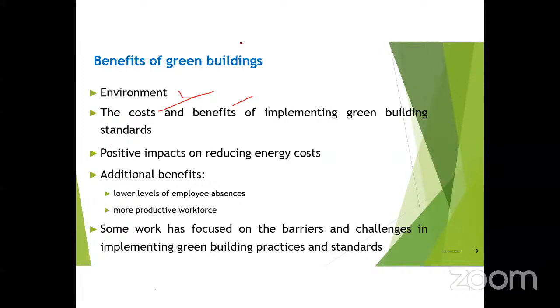Now I will tell you the best example. I don't know if you read it, there was a news item in the paper, actually from Pune. What happened? A couple is staying in a house where they don't need a fan even in the summer season. Even in May they don't need a fan. Why? They have used the natural property of the soil. Below 1.5 to 2 meters, the ground temperature is constant. So what they did was flow a pipe through the whole building, and in that pipe they flow water, and that water is cooled whenever it goes below the ground, and the cooled water is then lifted, and this process goes on. So the indoor climate they kept.